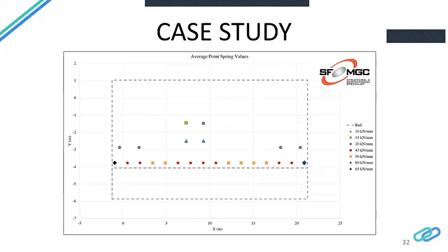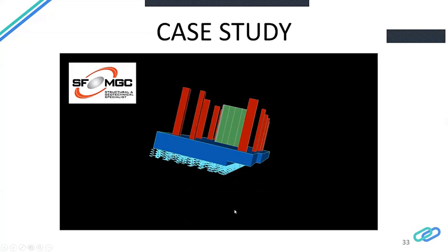And this, for example, you can see the areas, the point springs or the stiffness of the piles, exported to be verified by the consultants, because usually they cannot use the coupling between the geotechnical and the structural model. So instead we are providing them with the stiffness of the piles, based on the worst case stiffness values. In the structural model, you will see that the soil is represented as springs, which are Winkler springs, or some developed version of Winkler springs, and the piles as point springs. This is the soil as area springs and the piles as point springs.